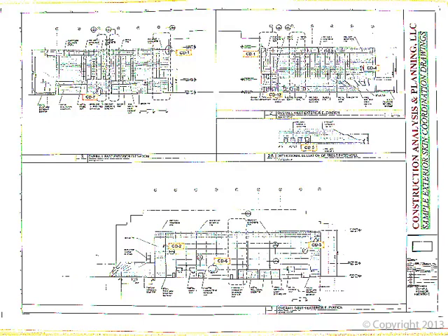Let's start in the top left. CD1 flags where we need to coordinate the expansion joint cover up and over the roof parapet. These are traditionally very difficult details that require coordination of the expansion joint cover, parapet cap, flashing, roofing, parapet framing, backing for the expansion joint cover, and of course the existing building wall. Now the existing building wall may look like the easy part here, but keep in mind that the existing building facades rarely happen to be flat and smooth. So we've got to take into consideration any bump outs, reveals, or other special conditions during our skin coordination effort. With all these factors, CD1 may eventually be broken out into 7 or 8 individual details.